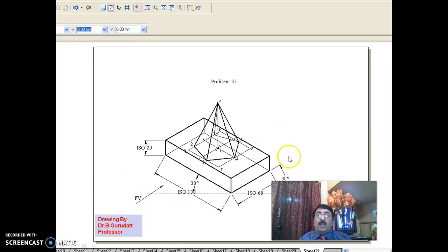Now if you do this way, you know very well I have taken the front view, because the condition in the problem is, if you see in the front view, the longer side of the rectangular prism is parallel to VP, but that condition has not been given. But one condition is given: a side of the pentagonal pyramid is perpendicular to VP and to the left of the observer. That condition is met. This is okay. In that way I have done this, because for the bottom solid they have not given any condition. That is why you can take any of the conditions for the bottom solid.